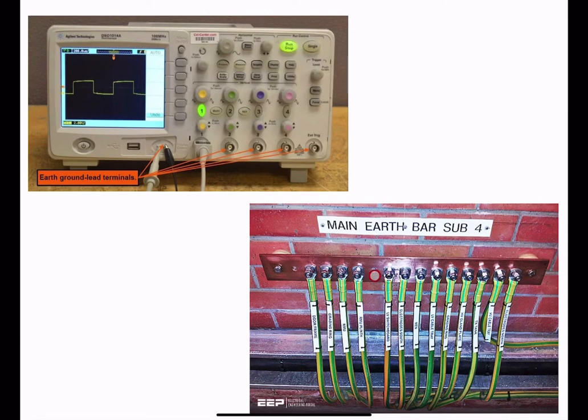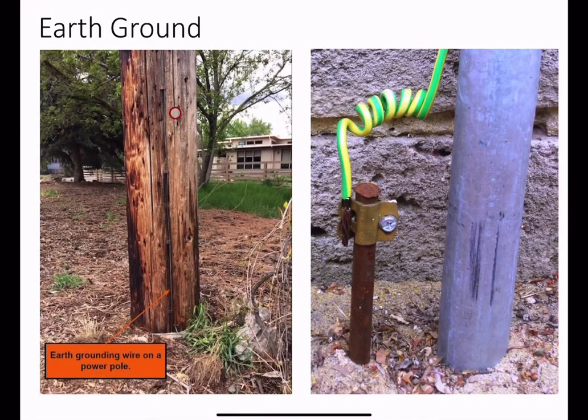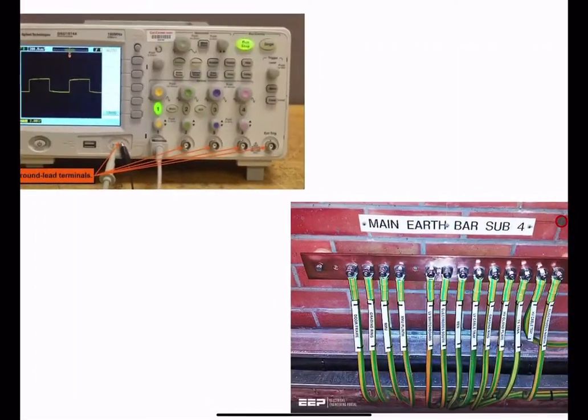It provides electrical connections and we can connect all the electrical appliances directly on this copper strip, and this copper strip is then connected with this rod or this type of wire, which eventually grounds the current, and this is how grounding of appliances is performed.